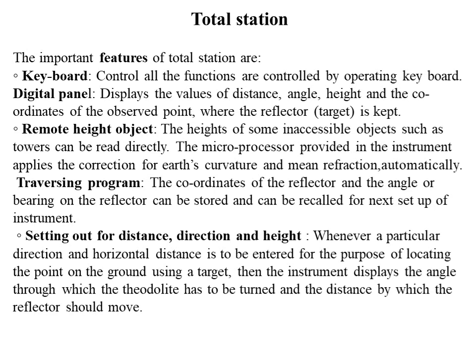The microprocessor provided in the instrument applies the correction for Earth's curvature and mean refraction automatically. Then traversing program. The coordinate of the reflector and the angle or bearing on the reflector can be stored and can be recalled for next setup of instrument.